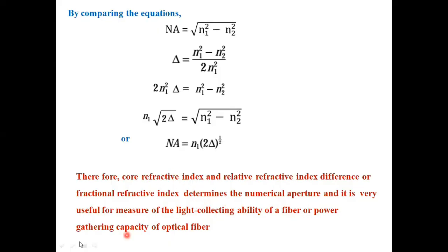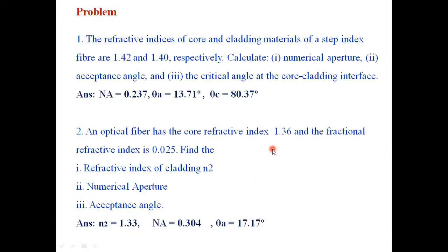The numerical aperture defines the maximum power gathering capacity of the optical fiber, which depends purely upon the core and cladding refractive index or the relative refractive index difference.